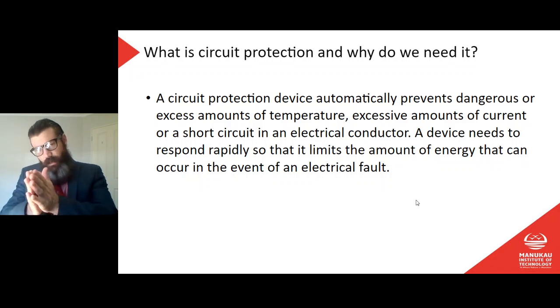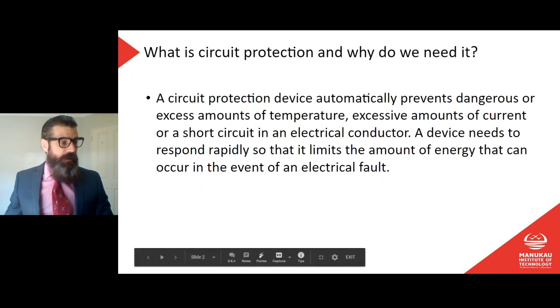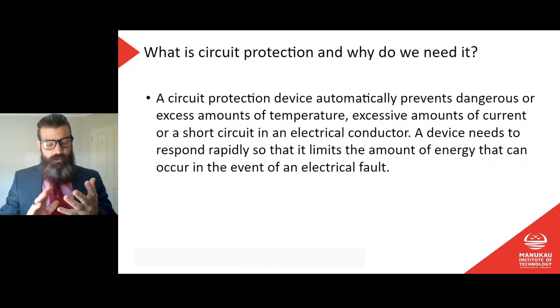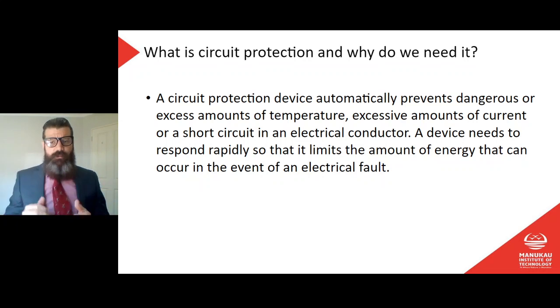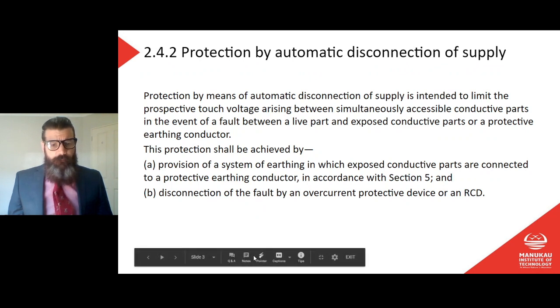And then everything after that circuit protection, we ensure that the current carrying capacity, or the ability for that conductor, fitting, device, whatever it is, to draw current or to supply current, is greater than the maximum breaking or cut off current of our protection device. That makes sense. That's fairly obvious.